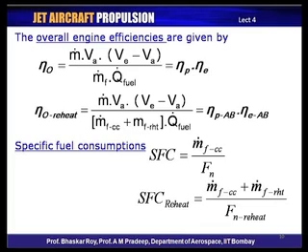The moment you have a reheat engine, you have two rounds of fuel burning, once in the combustion chamber and again in the reheat zone, and obviously the SFC is going to go up. Now, you are hopefully creating more thrust through this reheat. So, even though your fuel consumption is going to be almost double, your thrust production is going to be pretty high, if not double, and hence your SFC is going to be a little on the higher side, but hopefully not exactly double. So, you are creating high thrust most probably at the expense of a high SFC.